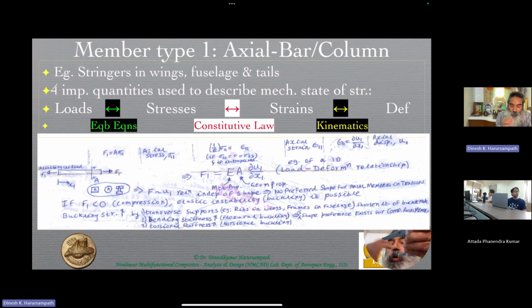The other also, because the chord is much larger compared to the thickness of the airfoil. From both the geometry as well as the load point of view, this bending is not that much of a concern, the bending stiffness is fairly large and the loads are small, and therefore you would not have that much of an issue as far as buckling in that mode is concerned.